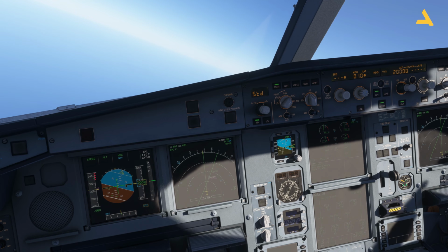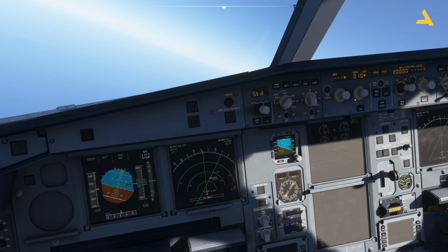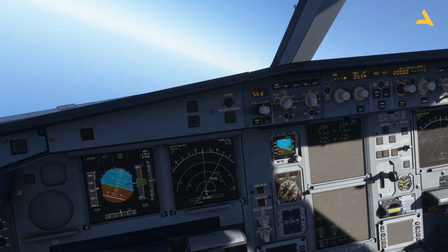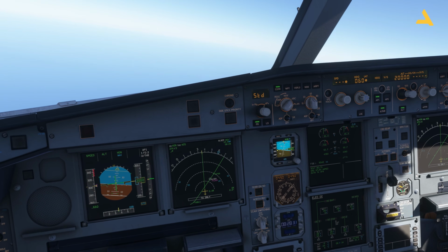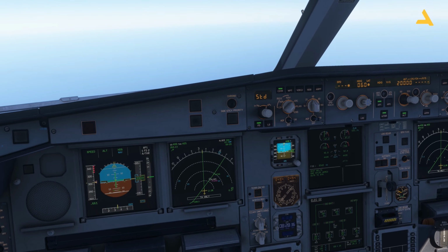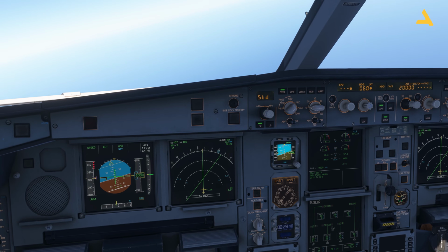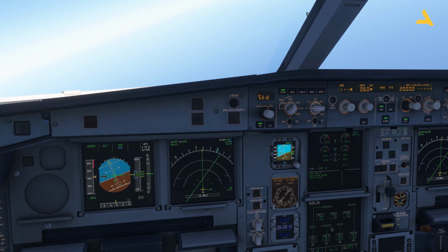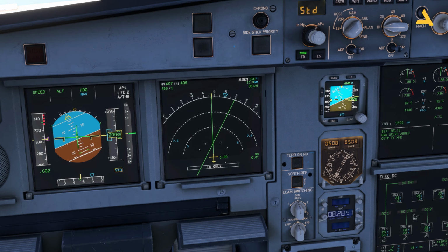So that's how you fly this plane. In the heading mode, let me adjust it, and let's keep it over here, 60 degrees. Now I'm going to intercept this line. Deviation is 1.2 nautical miles towards the right side from the flight plan.